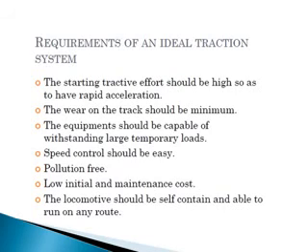The group which consists of vehicles which receive electric power from a distributing network, fed at suitable points from either a central power station or substations, and this group can also be subdivided into systems operated with DC such as trolley, buses, tramways, railways, or systems operated with AC like railways.